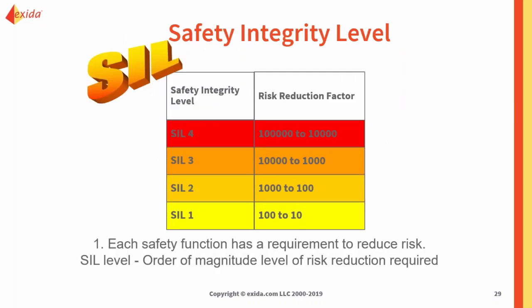The great thing about the standard is it provides you the charts already there for you. So you flip to IEC 61508 or IEC 61511 and you look up the SIL level and the risk reduction charts. So for our example, we fell smack in the middle of SIL 1. So for this example, you could say, well, to open the doors, you need a SIL 1 with at least a risk reduction factor of 50, because there's part of that SIL 1 that wouldn't make it. Or you could just say, I could use any possible SIL 2.